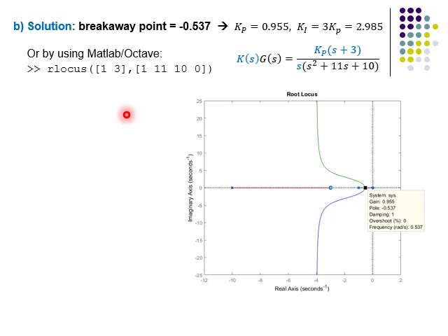Okay, so this is the result of using the command. We generate the figure shown here, which shows the root locus diagram, the same as or similar to what we sketched earlier, and by clicking on the locus we can find the value of the breakaway point and the corresponding value of the gain Kp. So this is a good way to check the solution is correct, although in this case we can calculate the solution ourselves algebraically.